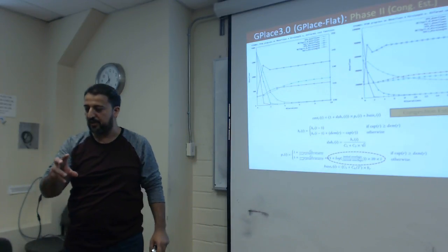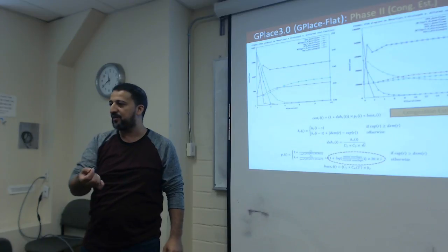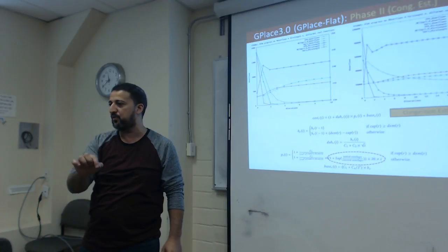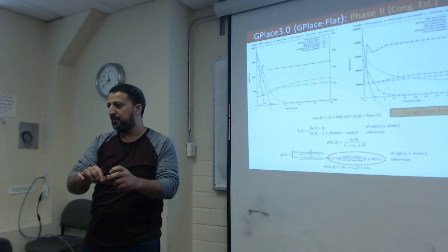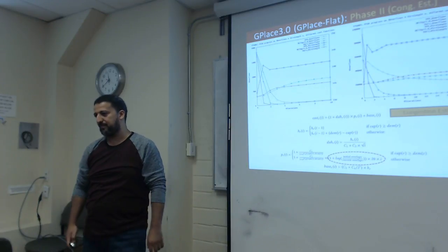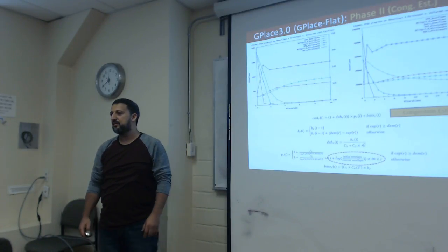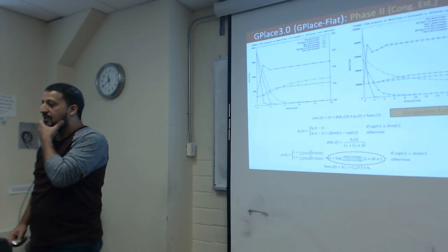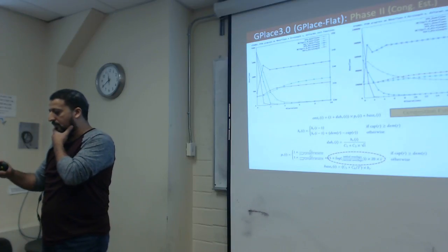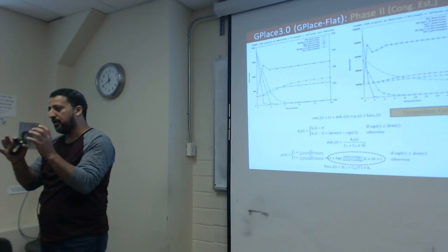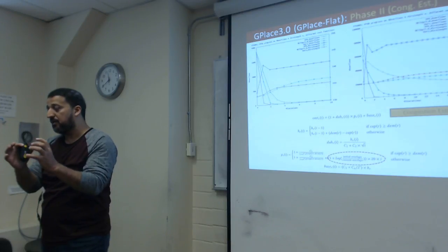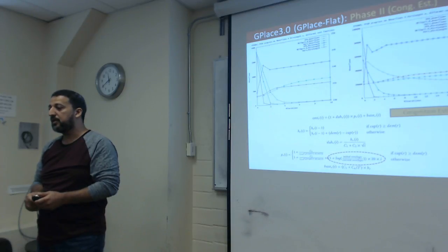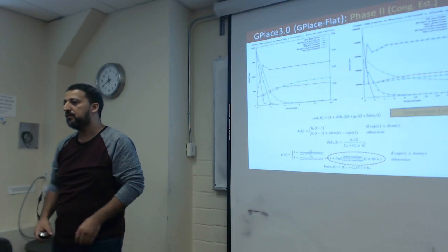because we have some limited connectivity within the switch, we add some approximation to this, based on the pin count. So you sort of scale down the capacity. What do you scale it down to? What do you find works well? Do you scale it down by 70%, 30% or something? It depends. It's a variable of the pin count, some constant that's fixed, always multiplied by a pin count of a switch block in the device architecture.